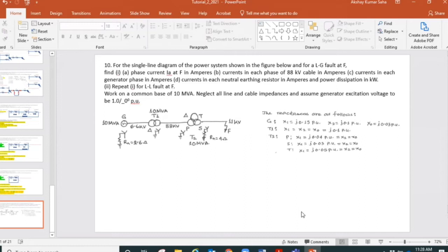If you want to express them mathematically. But in our real life, we don't get them from a generator, because of the positions of the rotor or the magnetic field as they change from position 1 to position 2. It is always a step, no matter how small that step is. So we get a composite waveform, and then we get all the harmonics in it, but the fundamental one is the highest one, then the order is increased, but the magnitude of those harmonics will get reduced.